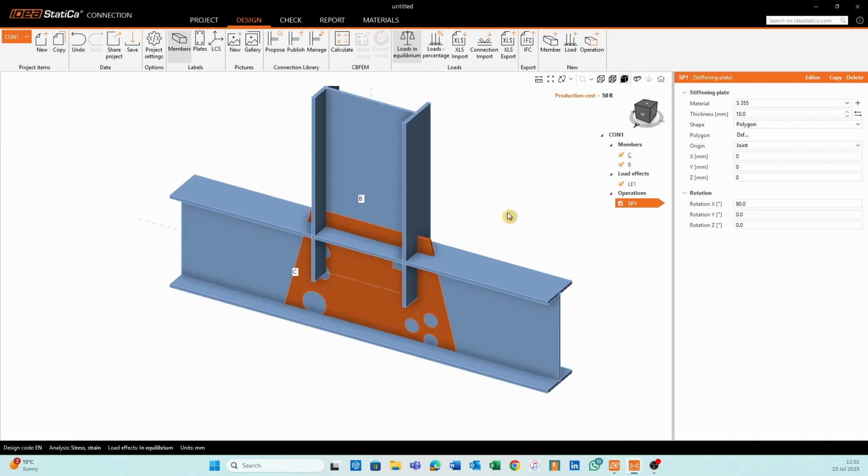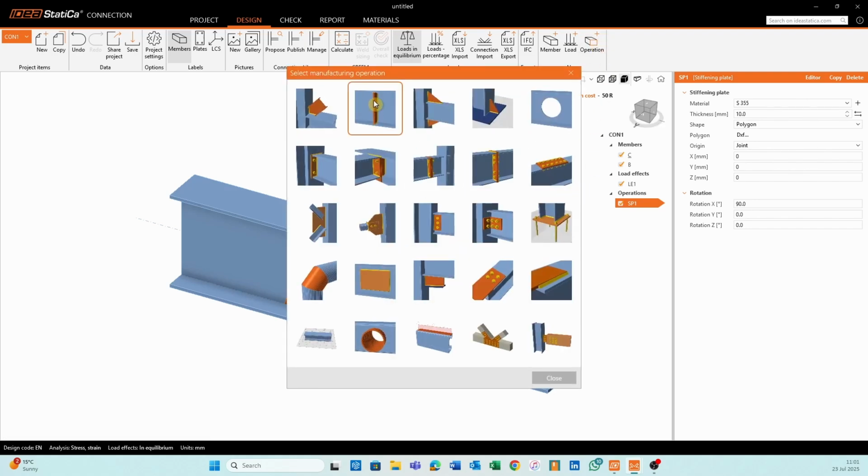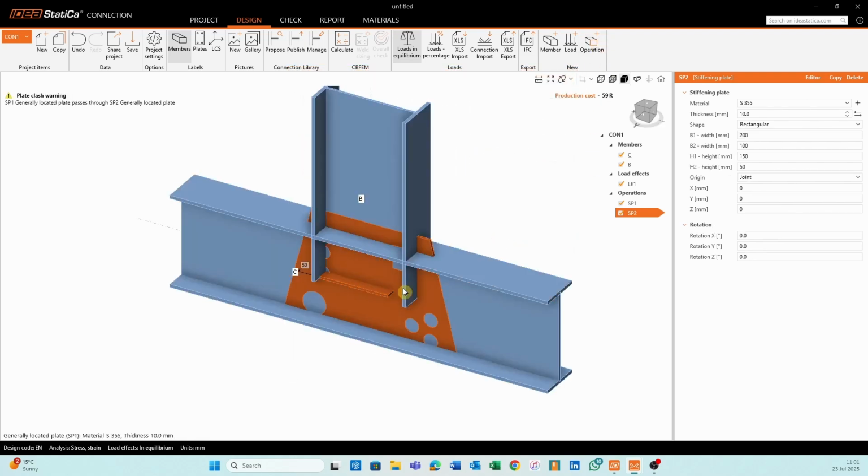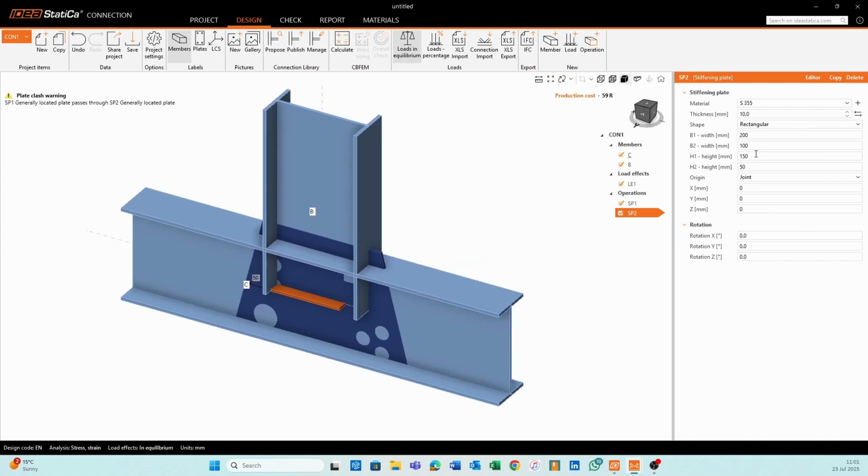Now, the first thing I want to do, I have this plate here, so I'm going to leave that there for now. I'm going to create a bottom plate. That's all good and well. I am going to set its width. Let's just see in which direction that goes. So it should be 375 and 375. Of course, I'm aware of what the geometry of this plate should be. That's why I know what these values are. And then this is 180, so that should be 90 and 90. My Z offset value is going to be 205.